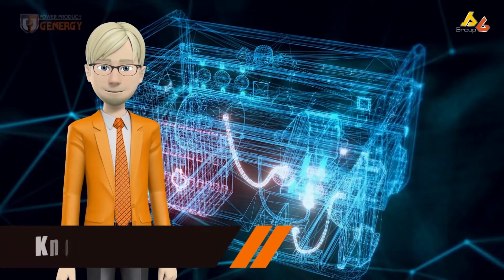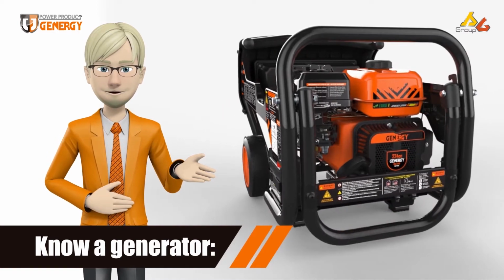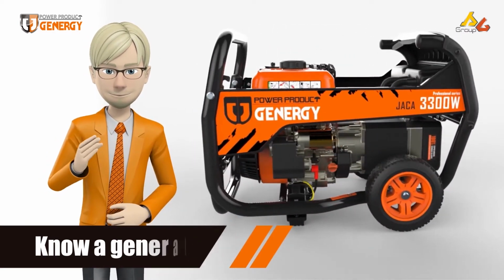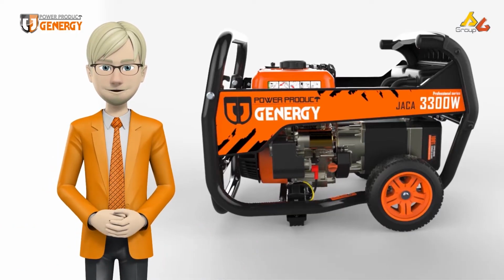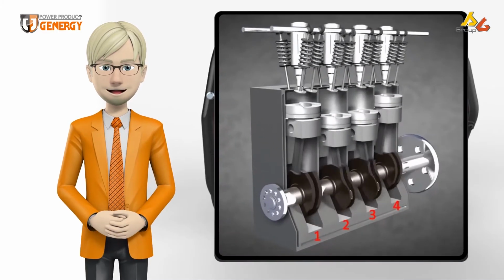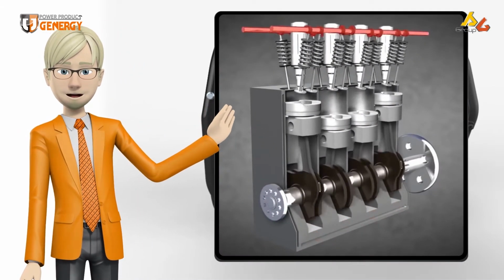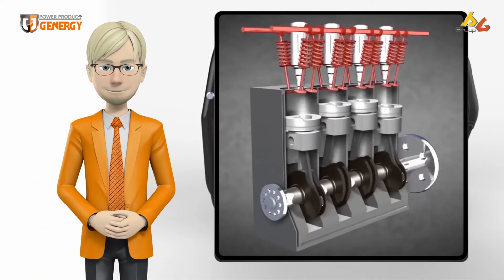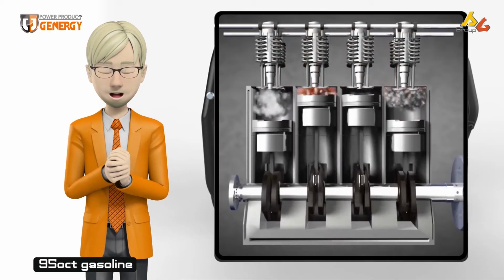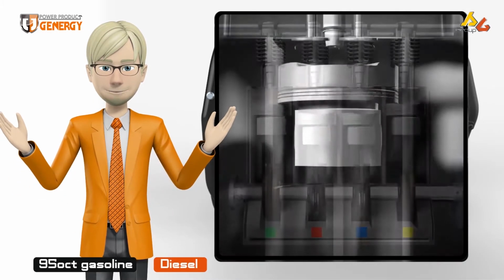It goes without saying, but let us start by describing an electrical generator as a machine that transforms mechanical energy into electricity. This initial mechanical energy will be obtained through 4-stroke combustion engines, one of the two most important parts that make up a generator. These engines are going to be fed by different types of fuels. The most common will be conventional 95-octane gasoline, but we can also find options for diesel or even propane and butane gases.